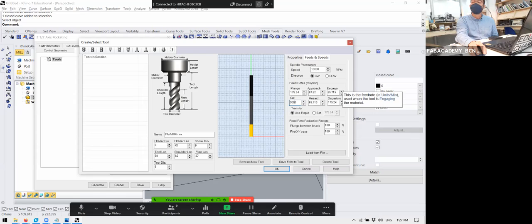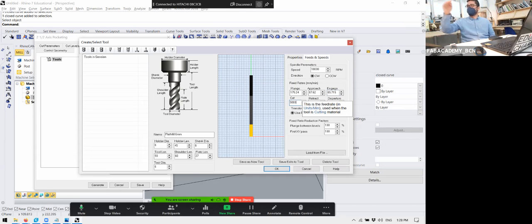Is there any guide for this, to know the speed for each material? Or the chip load equation? Actually, what the group assignment is, is to find this value and do different tests at different speeds to see which one actually gets the better results. And in general, in wood, it's not the same cutting in this direction than cutting in this direction. So you need to test angle lines, squares, and circles to actually get the average speed.